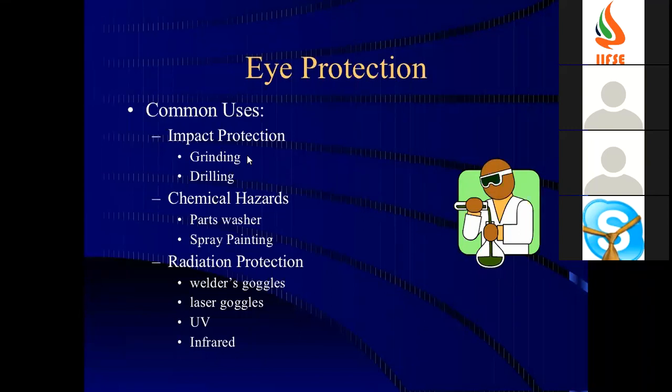And we have discussed regarding the mechanical hazards. We discussed what the standard mechanical hazards are, like ENT and ICE. I told you to remember ENT hospital or ENT doctor. ENT means entanglement. That is the first primary mechanical hazard. ICE: I means impact, C means contact, E means ejections. Ejections are the hazards involved in grinding and drilling.